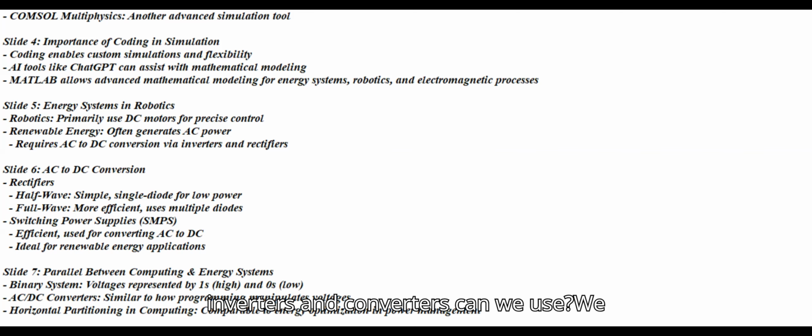What inverters and converters can we use? We can convert AC to DC using rectifiers, which come in two types: half-wave and full-wave. Half-wave uses a single diode for low-power applications, while full-wave employs multiple diodes, like a bridge rectifier, for better efficiency.